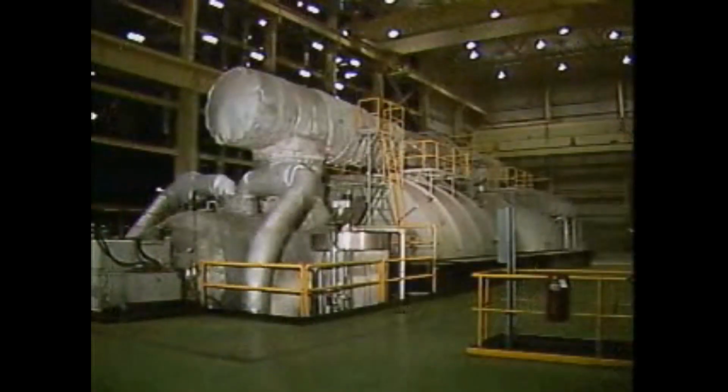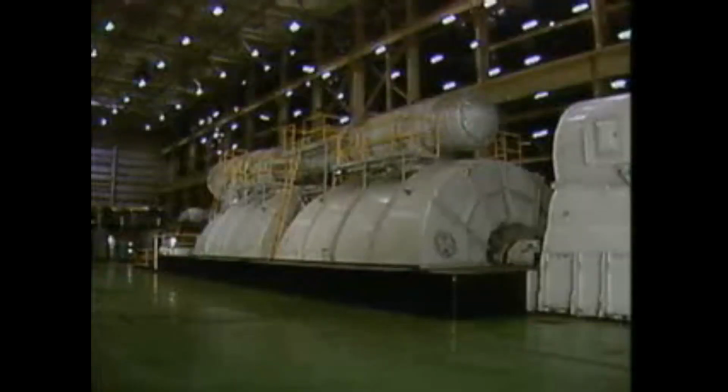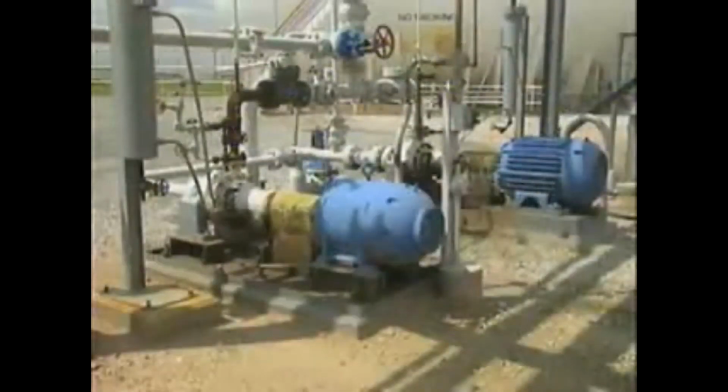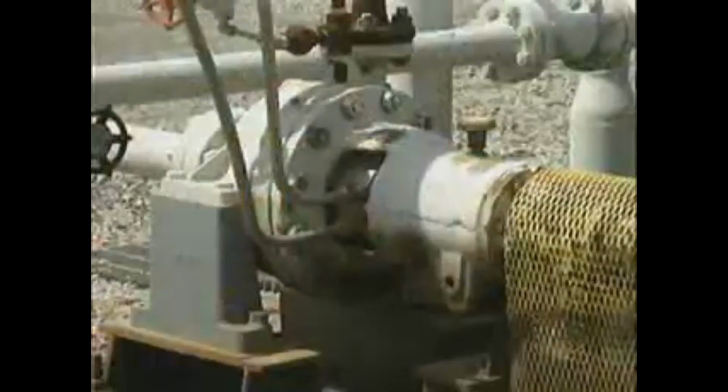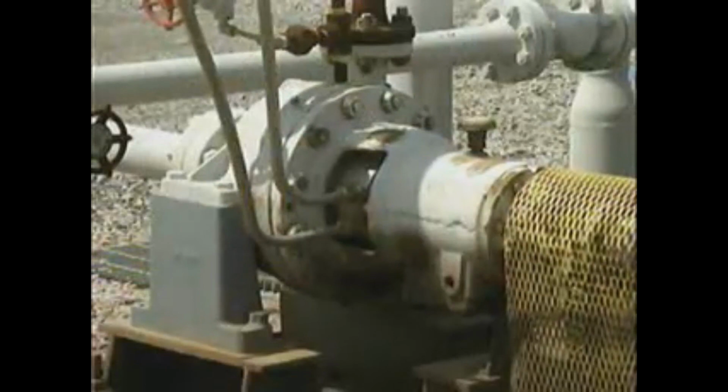Sometimes, though, the same circulating oil is used for both lubrication and hydraulics. For example, large steam turbines are often built to use the same oil for lubrication and for hydraulic control. In equipment that's operated in low temperatures, a circulating oil's pour point must be low enough to allow the oil to flow freely. Also, the viscosity index of a circulating oil is very important if the system in which the oil is used experiences large changes in temperature.